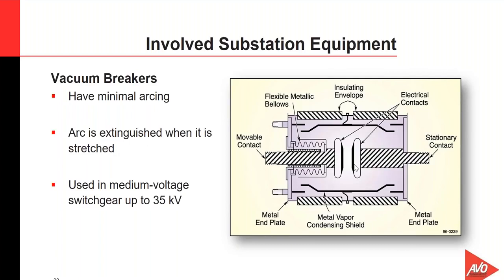As far as testing is concerned with this vacuum type of bottle interrupter, really the only test we can perform to check this vacuum bottle is our vacuum bottle integrity test used with an overvoltage withstand tester, applying a DC voltage and testing this. And of course, it is a go or no go type test. All right, it's either a pass or fail test. That's all it is.